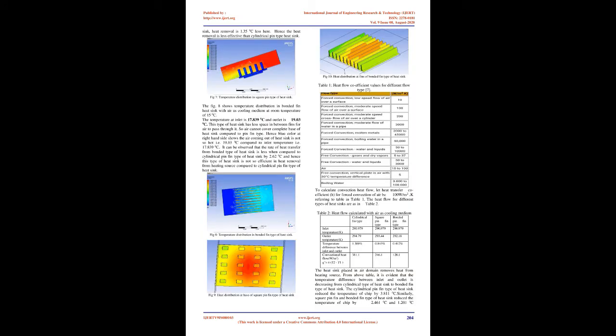Calculation activity: here the file where data is to be saved is chosen, along with all the quantities which are to be calculated. In this work, temperature, pressure, and velocity are chosen. Frequency, time step 3. This is because the output will be calculated thousands of times and there is no need to save all data. This is the instruction for Ansys to save one output after every 3 outputs. After giving all the instructions to Ansys, the results provided by Ansys are as discussed below.